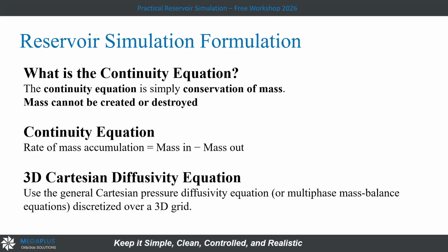The diffusivity equation, or 3D Cartesian equation, because we have another thing called the radial diffusivity equation. It depends on the shape of the cell. The general Cartesian pressure diffusivity equation depends on the continuity equation, or the mass balance equation, and Darcy's law, that we will see.